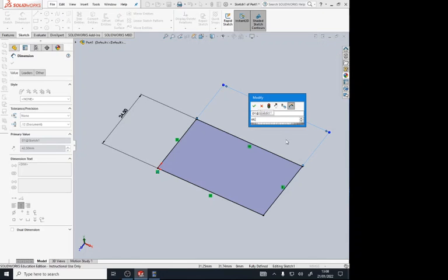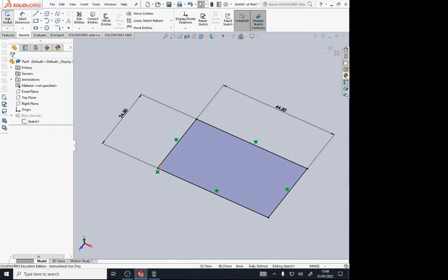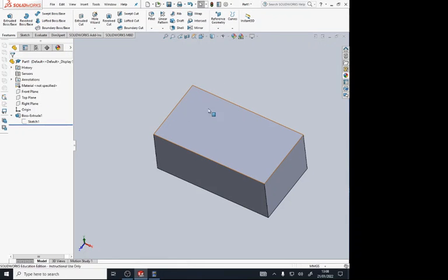So this is going to be 44.5. Type it in. It will automatically just extend that box out for you. And then if you press tick and then exit sketch in the top corner, it will automatically adjust the length of our cuboid for us as well, because we've adjusted that initial sketch which we were working from. That's a really nice feature to know about, especially if you are going to go on and do technology in year 10, 11 and potentially 6th form as well. Being able to go back and make slight alterations is one of the really nice features about 3D CAD software.